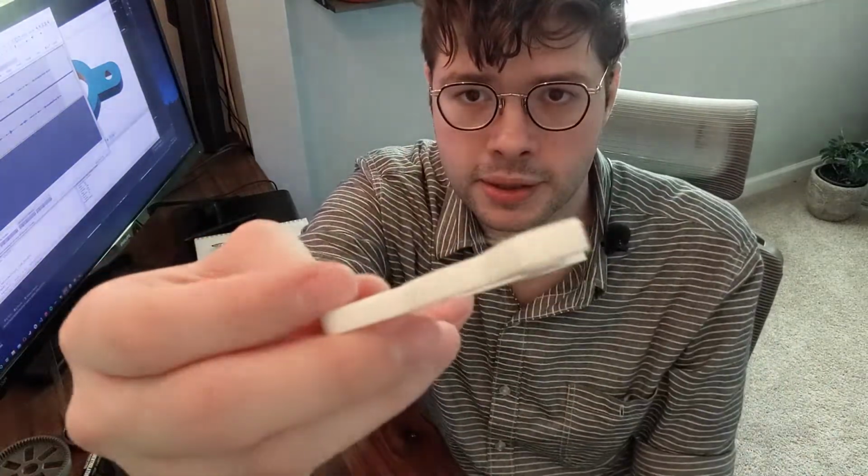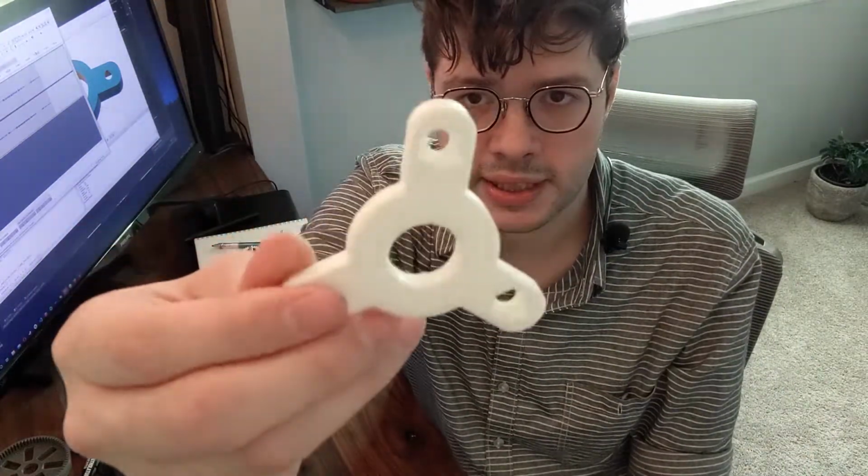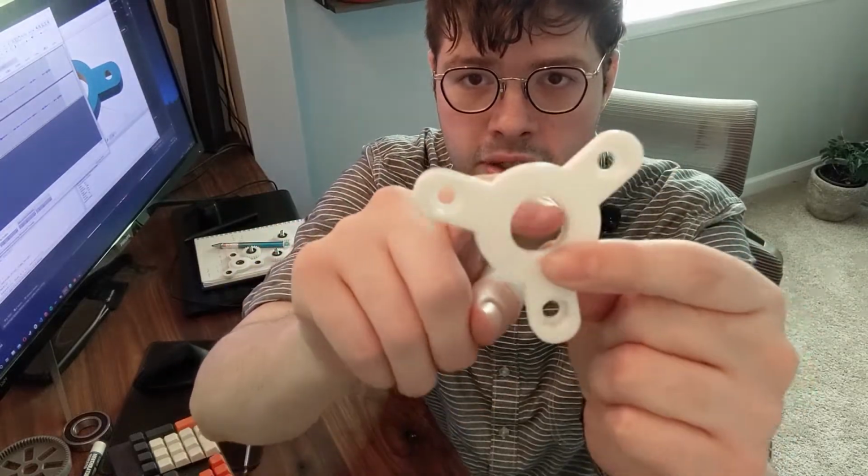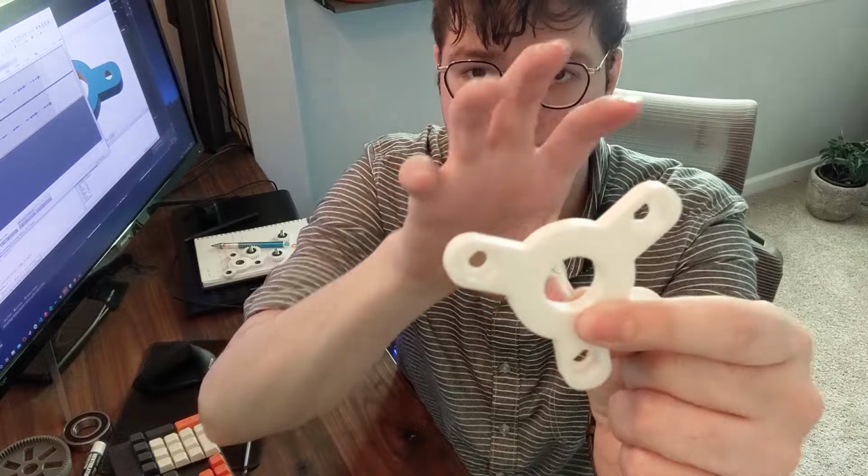The first design consideration that I want to discuss is how do you actually attach the gear to the arm? So this is an example of the arm assembly. It is a piece which looks like this. It has 3 holes for the planetary gears, a space for a bearing, and then the sun gear will go there. So how do you actually attach a gear to something like this?